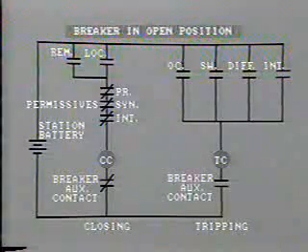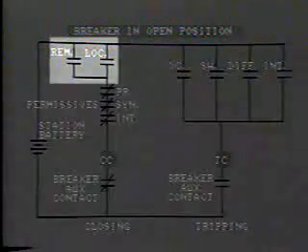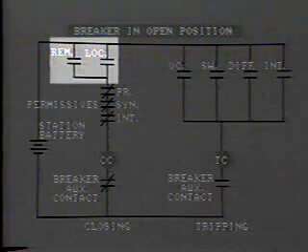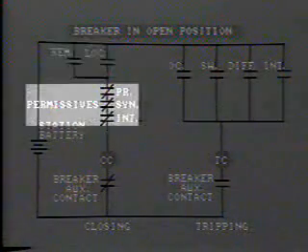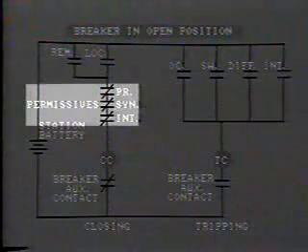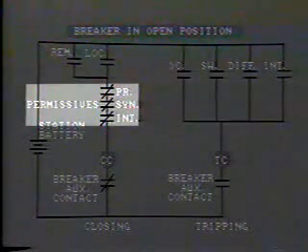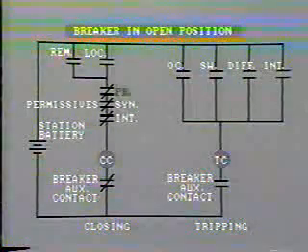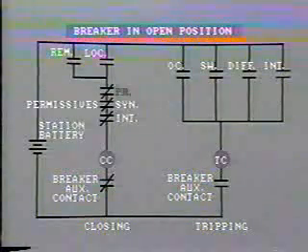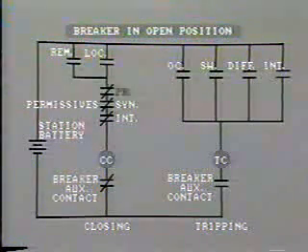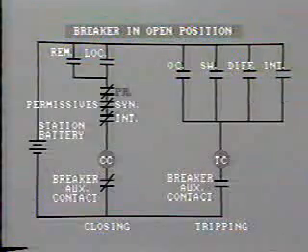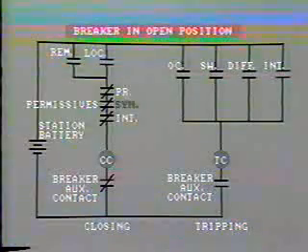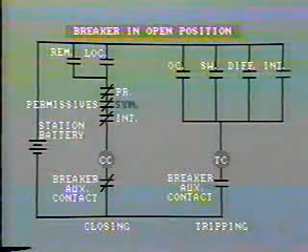You would think that to close the breaker, it would be sufficient to close any pair of the manual switching contacts. In this installation, we have local and remote operation. But look, there are other contacts in series with the closing coil, and these are known as permissive contacts. For example, this pair will only close when there is adequate pneumatic pressure available to operate the breaker mechanism. This pair of permissive contacts are only closed when a synchronizing relay determines that conditions are correct for closing.